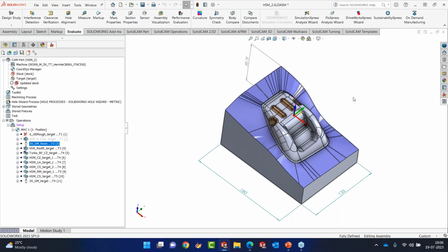But with diameter 12, it finds effectiveness with both. It's not really small, and it's also not very big. It's somewhere in between. It gives you a very good balance of a large diameter, yet the effectiveness of a small diameter tool. So next time you want to try iMachining on your molds, and if the part is relatively small, I would advise you to use diameter 12.